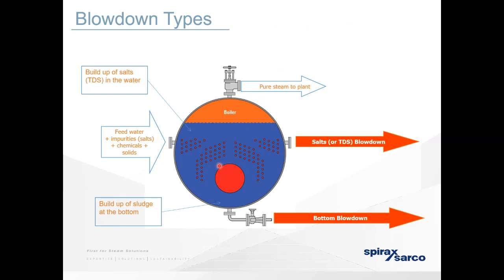As the scale builds, the heat that's reflected back in builds, and at some point, if this boiler hasn't been maintained, it hasn't been watched, the fire tube will collapse, which then lets all this water at pressure go into the fire tube, but you now have an open space. Where you have an open space, you then suddenly have flash, the expansion of this water into steam, and it creates a rocket effect with this fire tube.